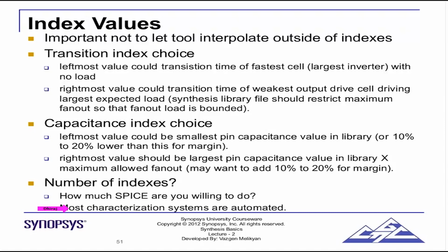So as an assignment, please go back, open whatever library you have, the 90 nanometer CMOS generic library. Choose one combinational cell, choose one sequential cell. For both of these cells, look at how the data is represented, what is the function given, how the lookup tables are given. Are you able to understand what is the max capacitance value? Look at the header, what is the delay type there, and so on. Just go through this lecture and map it to the library you see.